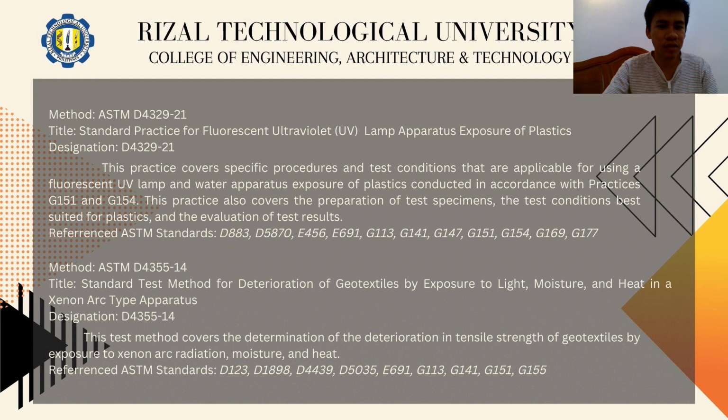D4329-21, Standard Practice for Fluorescent Ultraviolet Lamp Apparatus Exposure of Plastics. This practice covers specific procedures and test conditions that are applicable for using fluorescent UV lamp and water apparatus exposure of plastics conducted in accordance with practices G151 and G154. This practice also covers the preparation of test specimens, the test conditions best suited for plastics, and the evaluation of test results.